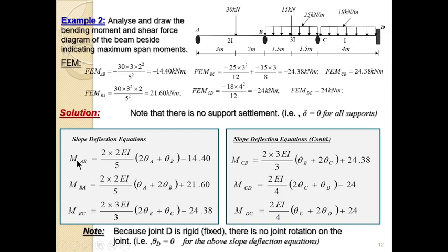So when we go to MAB at A, it is usually 2EI over L, but because I here is already 2, please take note of that. I here is already 2, so this is like 2EI. So the 2 is multiplied by the 2 that is already there.